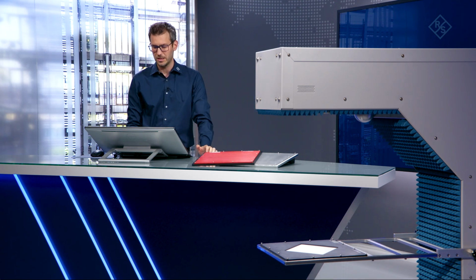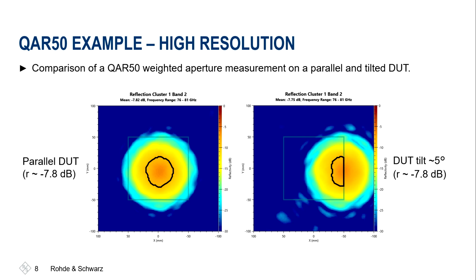We can see that with our measurement result that we did here. On the left-hand side, you see the result of the perfectly flat, perfectly positioned plate. The measurement circle is in the middle, and we are getting a reflectivity of about minus 7.8 dB. So minus 7.82 dB reflectivity for cluster 1 band 2, so for the 5 GHz band.